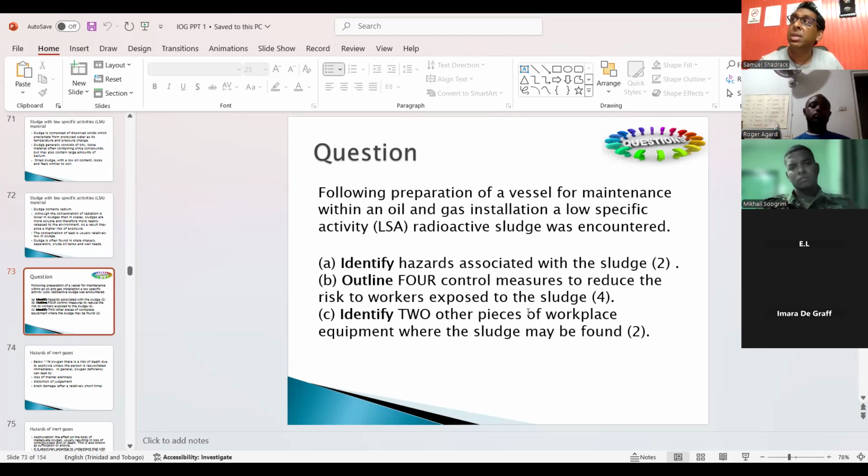You can talk about proper PPE, proper ventilation, maybe using some sort of mechanical arm, as I had mentioned, using a shovel. Maybe they could use something better today, but I still know they had sludge. You can't get rid of it anyway. If that tank has been resting for a while, you have to put a shovel to it, right?